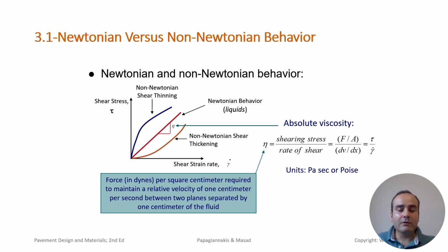At its core, viscosity is calculated as the ratio of shear stress to shear rate. This means that the viscosity reflects how the material's deformation changes in response to the force applied. If the viscosity is high, the material resists flow, behaving more like a solid.